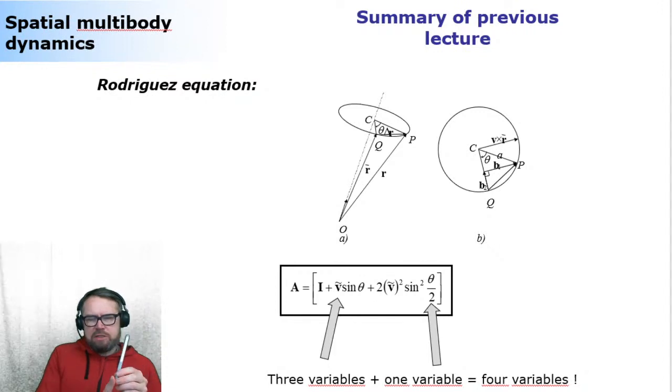You put this assisting vector at the origin of your vector, like this finger here is now representing this assisting vector. Then you can introduce the rotation around this unit length vector, and the amount of rotation is theta. Once you do that, you can use a bunch of mathematical manipulation, and you end up with a 3 by 3 rotation matrix, which uses 4 parameters.